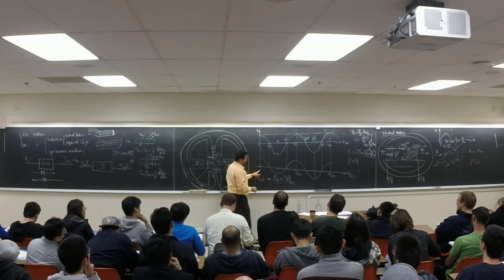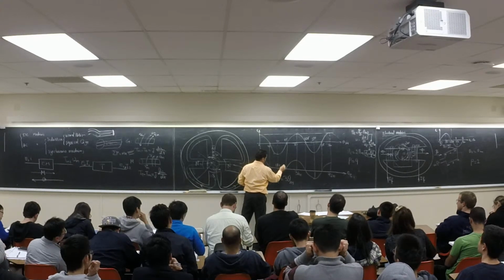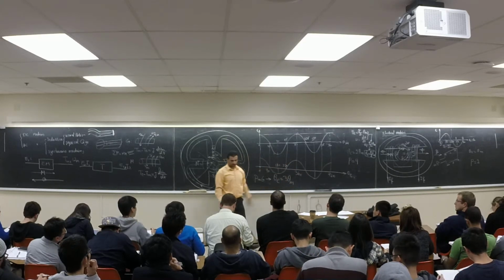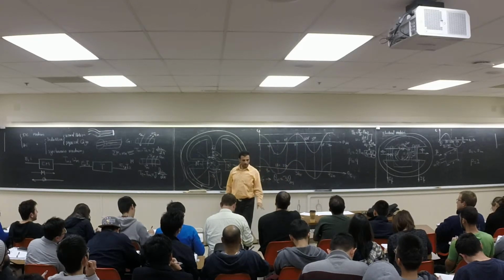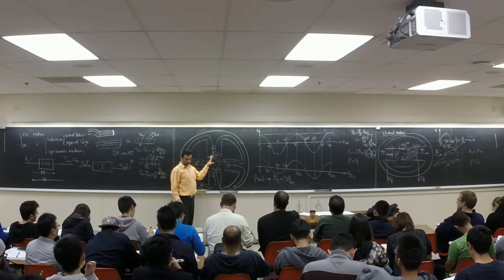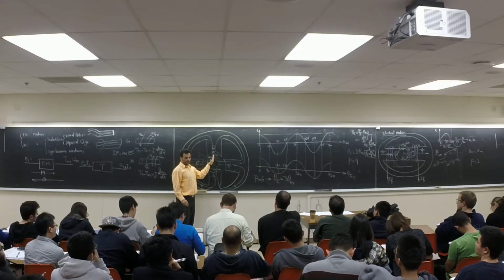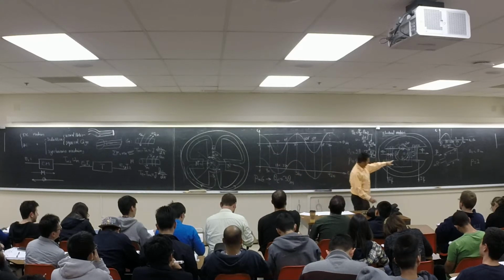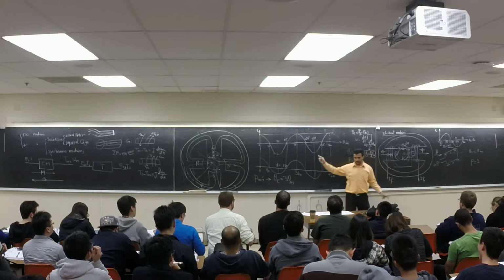So this is a 0, this is 360, this is a 90, 180, 270, and 360. This voltage I put here is electrical voltage. Why does it start at 90 over here? Because we started right under this pole, so it's max. If I would have started in the middle, it's going to start from 0. When I did that one, we started from here, between the poles. That was 0. And here I started right under the pole.